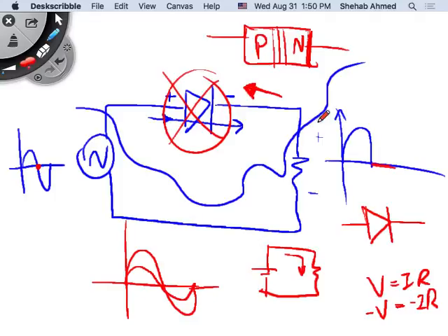When the device was forward biased, the depletion layer became very small, and you were easily allowing the charge, the diffusion current, to flow, and the device was conducting. When the device was reverse biased, the depletion layer was becoming very thick, right? And the barrier voltage was increasing. So the barrier to the diffusion current was increasing in that case.